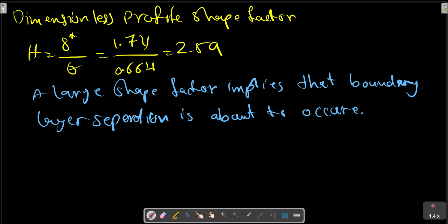If we plot the Blasius velocity profile from the relation in the form of the dimensionless velocity, which is a function of velocity over the velocity of the upstream, versus the dimensionless variable eta, we can see why the simple integral theory guesses. This figure shows the simple parabolic approximation of the Blasius velocity profile.